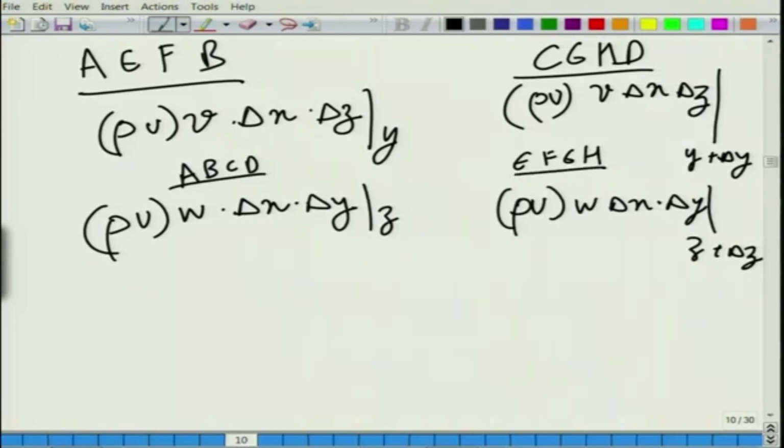Well, the idea is, how are we getting all these things? Because again the same thing, the momentum influx is nothing but it has the dimensions of q dot, but this is along your y direction, that is this direction. Because your area times the velocity, if you multiply this by the density, you will get kg or mass along the y direction, and that mass into the velocity will basically give you the momentum along the x direction, u being the velocity along that direction.